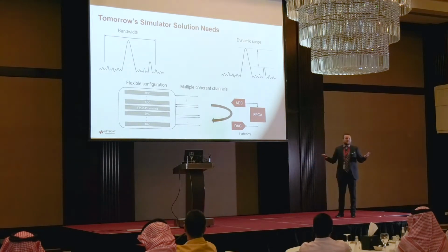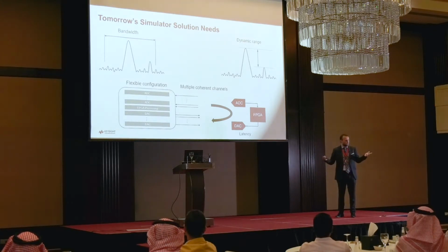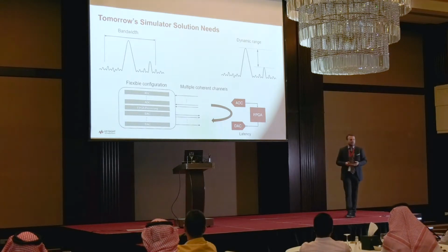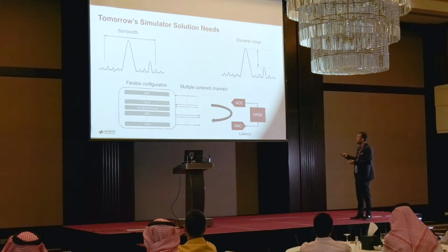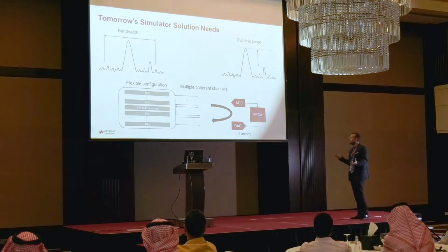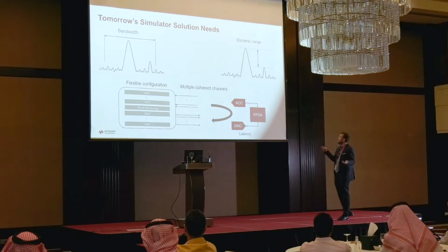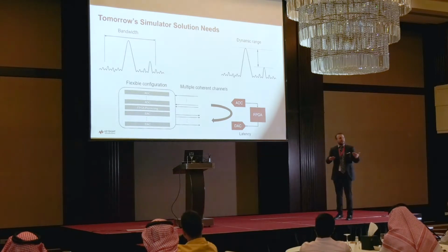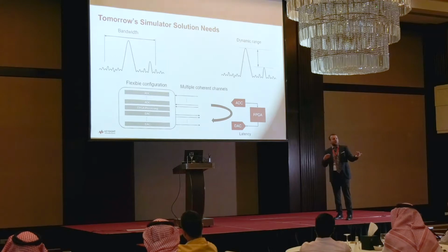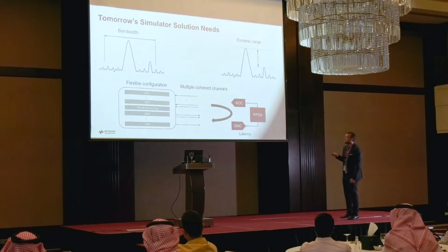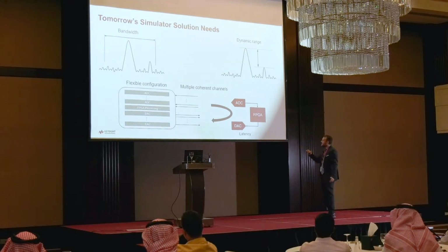As I mentioned, the radar systems today are looking to gather more and more data, and we do that through bandwidth and also from the resolution of our devices. So if we have very wide bandwidth, we can get more data from different frequencies. We can get more data points for Doppler and velocity. With more dynamic range, we can detect finer detail and return signals from larger distances.